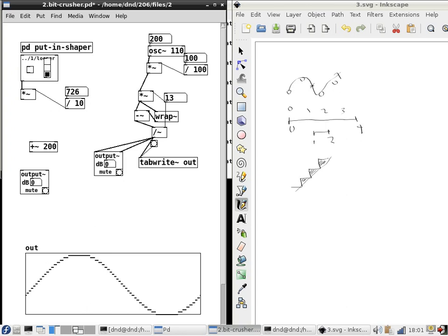bits you give it... This is called bit crushing because the original way of doing this would be to have a physical signal on a bunch of wires, which would be a binary number, and just drop the low order wires and keep the upper ones so that the thing lost bits.